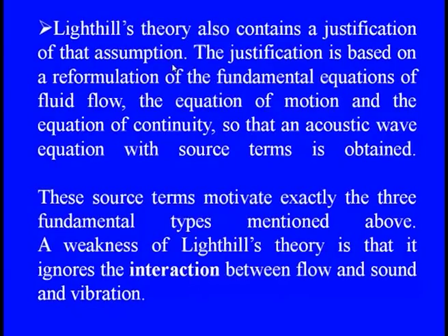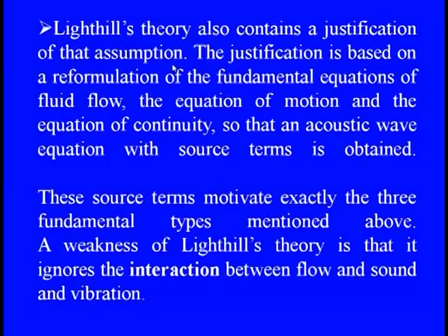The turbulence effect due to pressure fluctuations, when pressure energy is converted into velocity, means we need to consider its nonlinear impact. And the source terms are categorized into three main fundamental types, as we discussed already: monopole, dipole and quadrupole.